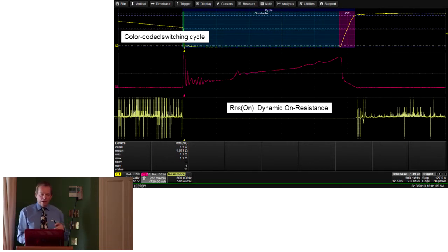But the problem with that is then you've got about, I don't know, 460 volts or 480 volts there approximately. But if you go down to 10 volts per division to make that fine measurement, you're feeding 480 volts into your front end, which is only set to 80 volts per division. So you overload your input amplifier, you can potentially damage your input amplifier, so you end up with front end overload. And that's something I've seen quite often. So people doing these sorts of measurements, such as power type measurements, where they need to do this type of thing, then they find the 12-bit scope very, very useful.